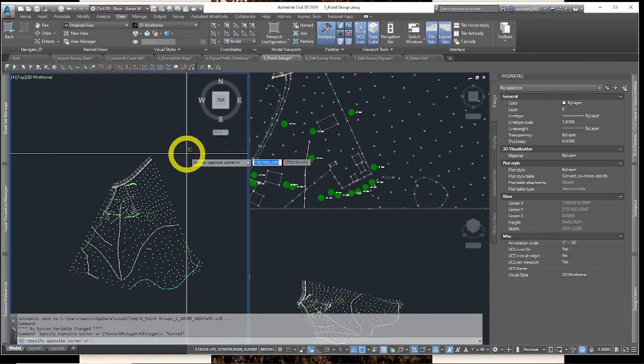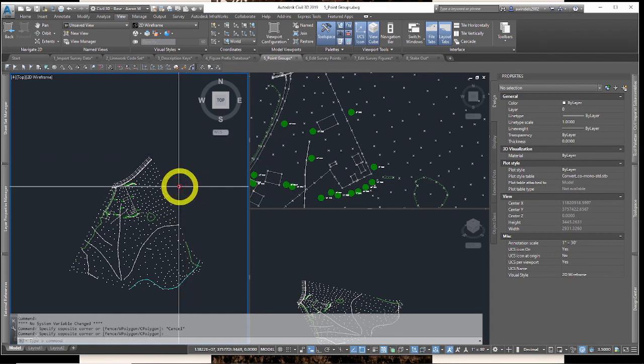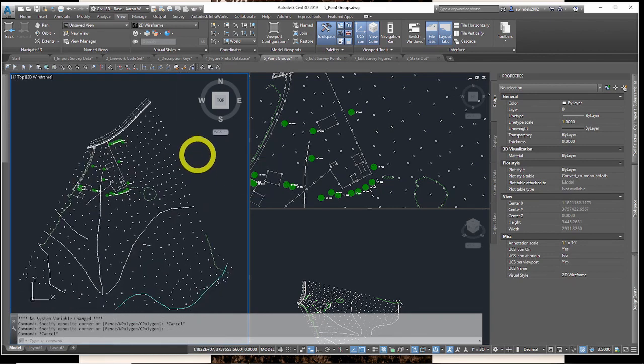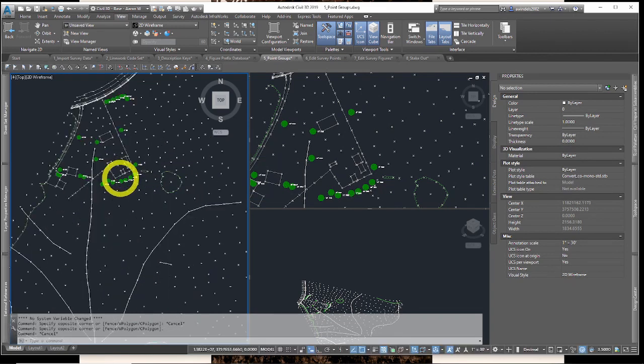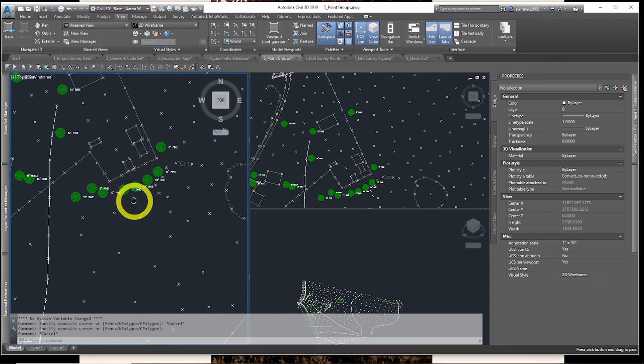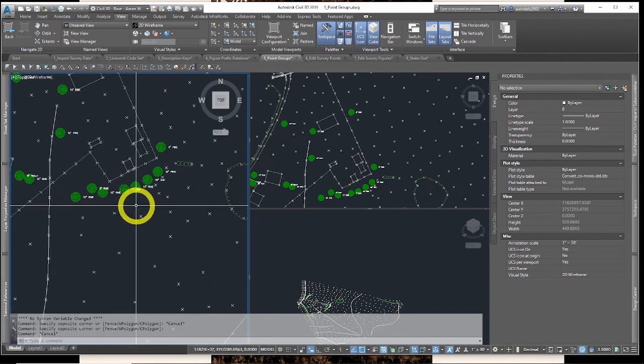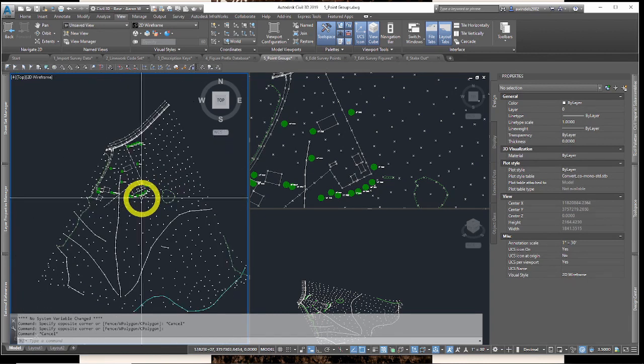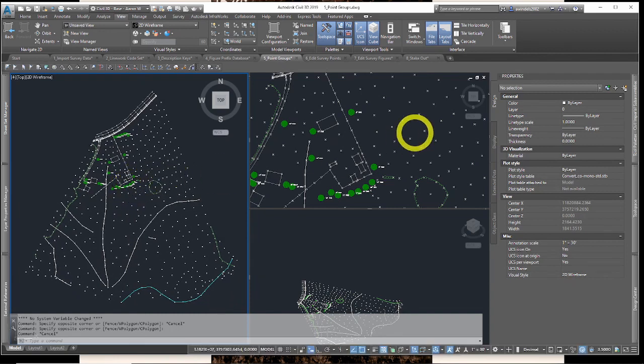Now, point groups are another way of managing large amounts of point data. The feature enables you to better sort your points. So your description keys arrange them a certain way initially. And the way I prefer to do Civil 3D when I bring in raw data, I like to dial my standards in with the description key to what our field surveyors usually do, and things come in initially very well because of a description key. And then after that, I like to use point groups, which are also pre-set up in a good template or CAD manager